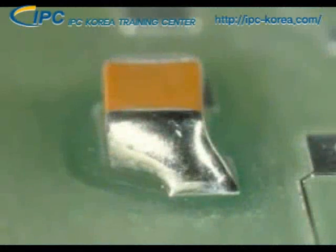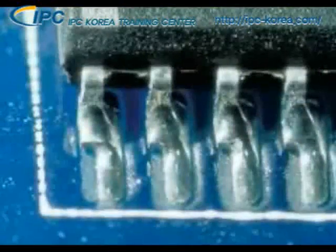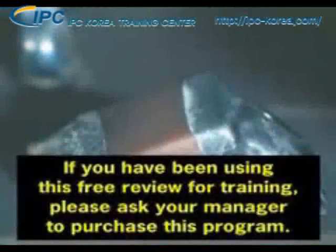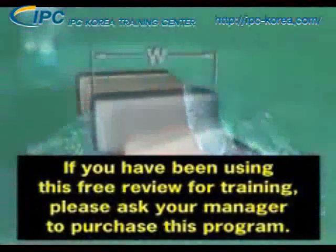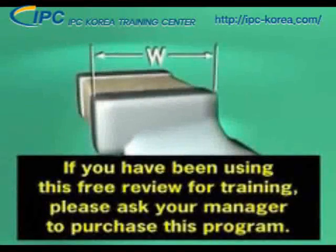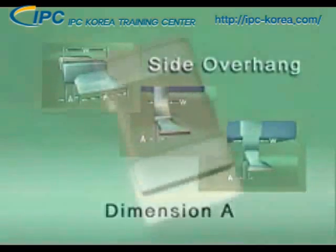The following examples show the limits of component misalignment and solder joint size for chip, J-lead, and gull wing components. Solder joints that do not meet any of these minimum conditions are considered defects. In these examples, the termination or lead will be identified as dimension W, and the land identified as dimension P. The first parameter we'll look at is side overhang, or dimension A.